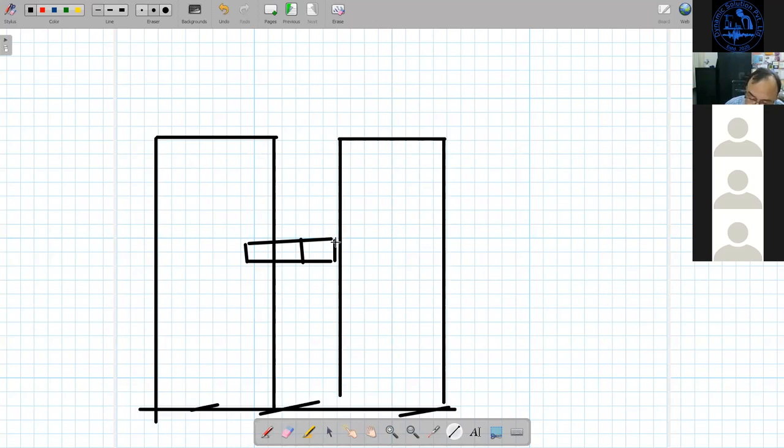So this steel member, when it gets damaged during an earthquake, can be replaced. We can connect it with bolts here. It can be designed like this. Some people are following this design. During an earthquake, this portion will get damaged. It will dissipate all the energy. And then after the earthquake, it will be removed and replaced by a new member.